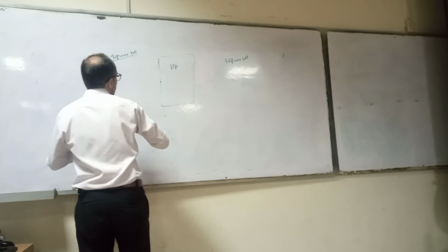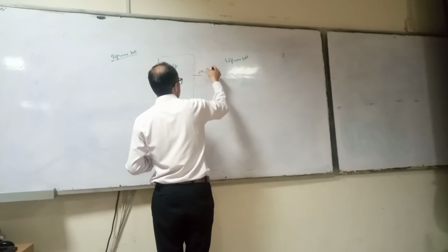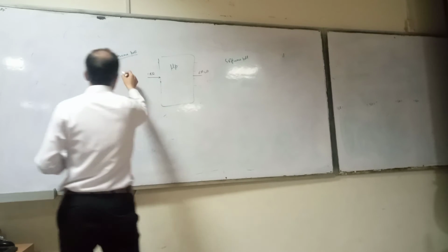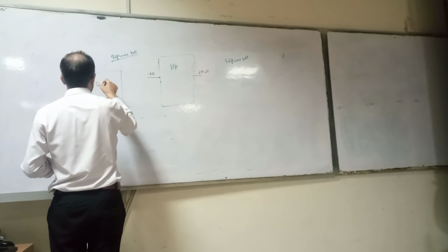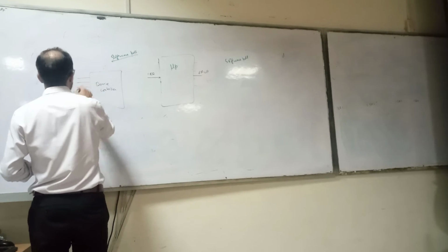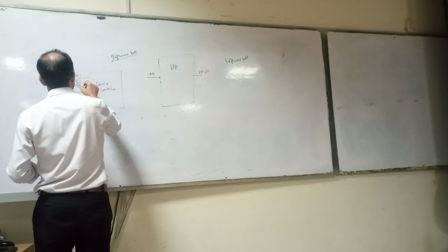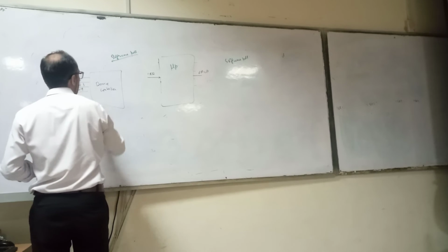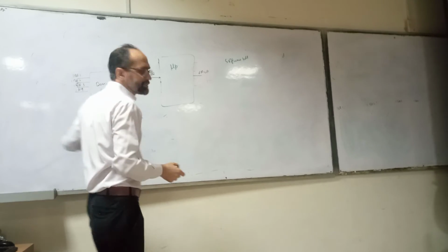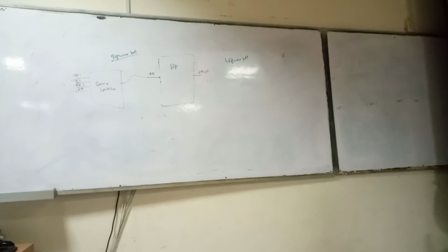In this mechanism you have a single IRQ and a single acknowledge. Now in this case there is some device controller and we have 4 interrupt requests: IRQ1, IRQ2, IRQ3 and IRQ4. If any of these generates a request, the microprocessor is notified that a request has been generated, but the microprocessor does not know who has generated the interrupt.